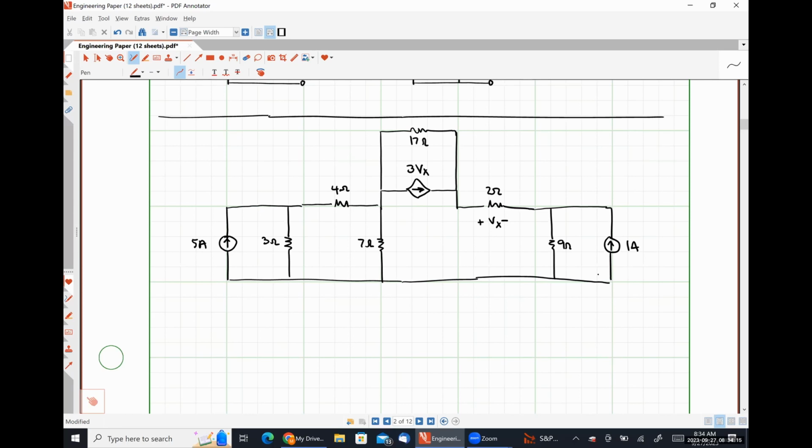Before we start on these transformations, and this is going to be another thing that'll be useful with this, is there any resistor combinations that I can make that would simplify this circuit? How? None of them are in parallel with each other, and none of them are in series with each other currently. So let's start things off here by doing a transformation for the practical current source to the left of this red dashed line, okay?